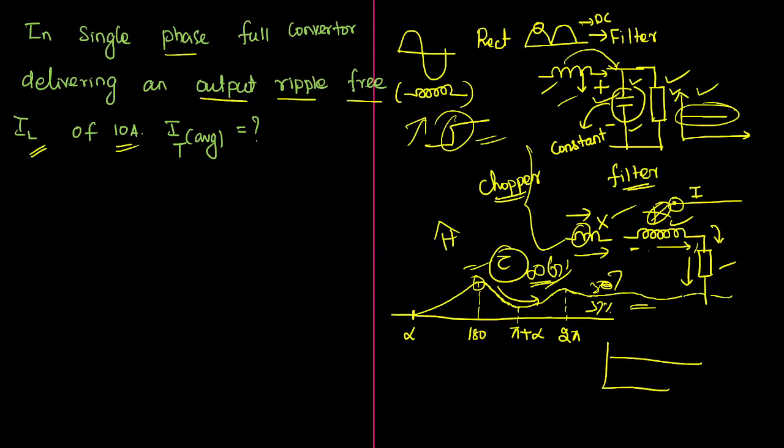Because basically we are calculating circuit turn off time only for the negative value of current, because that is called... In which place the negative voltage is blocked, we have to see, right? So you must first draw the waveform, take one pure sinusoidal waveform. Focus only on thyristor T1, see where it blocks the voltage, draw the waveform, then estimate the value of circuit turn off time.